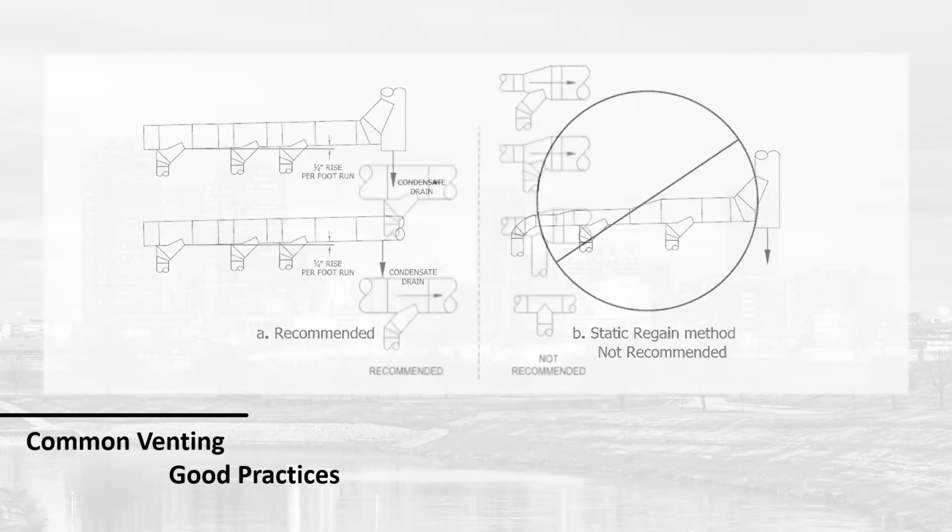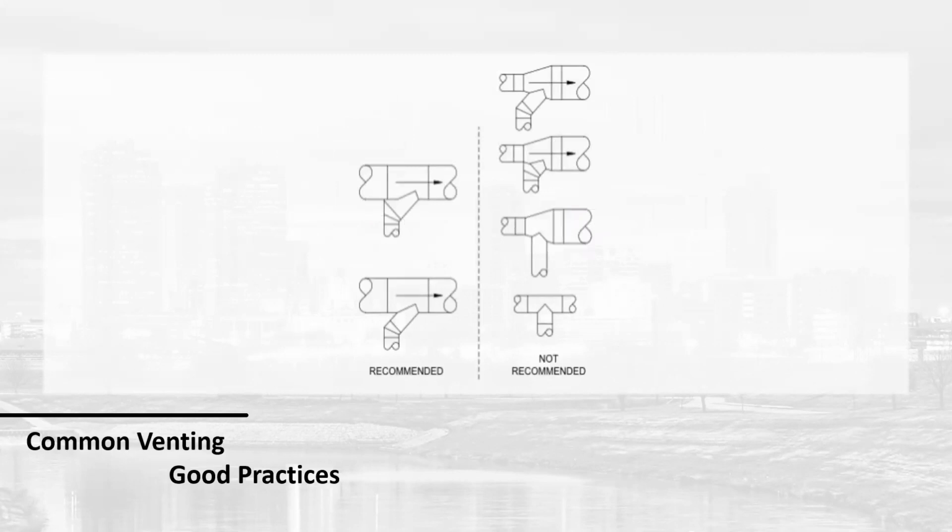The other thing is, if you learn nothing else today, lateral tees are your friend. Okay, flue gases are really stupid. They do exactly what you tell them to do. So if you tell them to bang their head against this wall, it's exactly what they're going to do. It creates a blockage, okay, becomes a turbulence issue. Okay, boot tees and lateral tees are not the same thing. Boot tees are better than straight tees, but they're not a lateral tee. A lateral tee is like merging onto the freeway versus stopping in a turn lane at a stoplight versus a four-way stop. Okay, that's your automobile analogy.